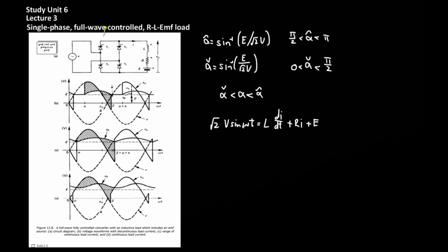Something important to note about full wave rectification is that because the sine wave is being fully rectified, there is effectively a doubling of frequency. This means that the load voltage frequency and the output ripple will be at twice the input frequency. So if it were a 60 Hz source, then the ripple and output voltage would be at 120 Hz.